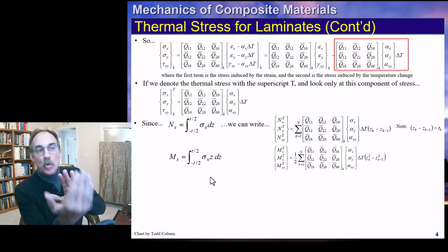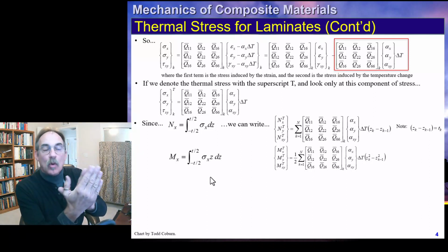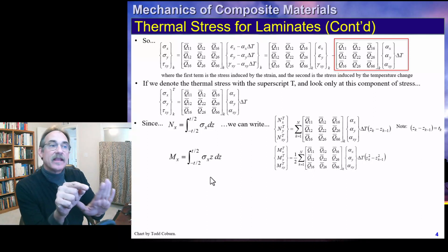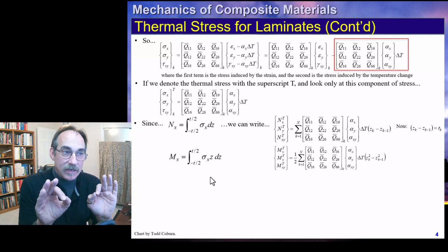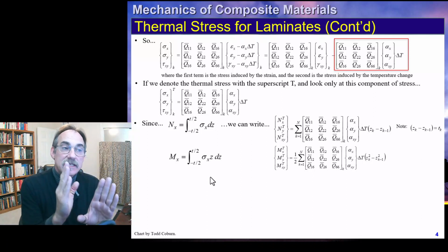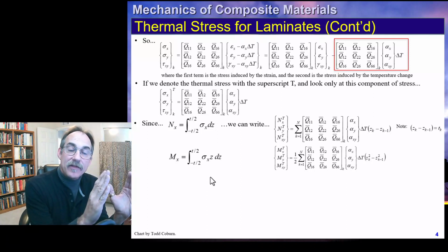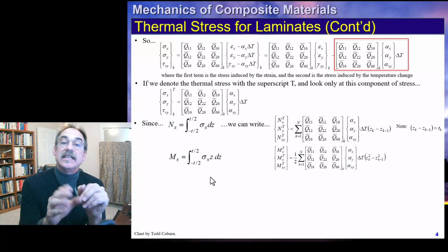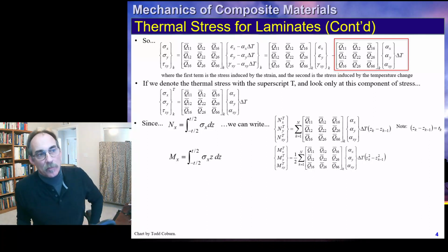So our virtual moments due to thermal, or the imaginary moments that would cause the same exact thermal strains, can be evaluated by taking the alpha delta T's pre-multiplied by the Q bar, all of that over 2 multiplied by the z_k squared minus z_(k-1) squared parameter, which can be written like this, as we saw before.